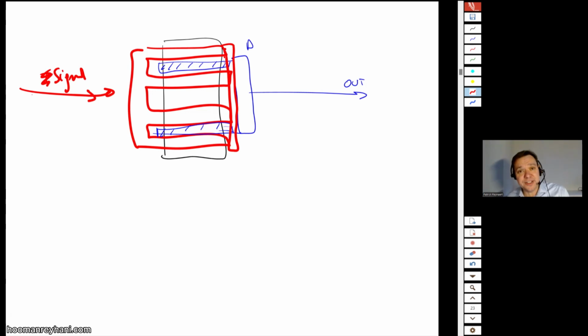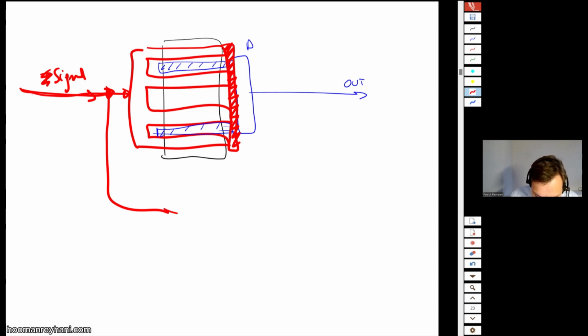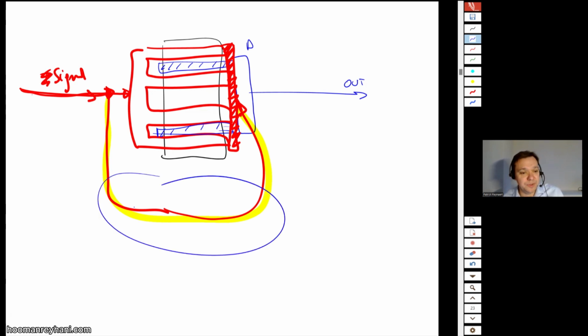And so, of course, we can just say, hey, let's connect them on both sides. But what I'm drawing here, this is not a connection on both sides because there is no current. Whether I put this connection or not, it's not going to make any difference. I have to somehow find a way that this current is split in effect in 2, and half of the current flows to the left and the other half flows through here. At high frequencies, this means that I'm introducing an additional interconnect here. Now that interconnect, the impedance of this interconnect is going to be significantly large, and there is no way that you can make sure that half of the current flows to both sides of the transistor.